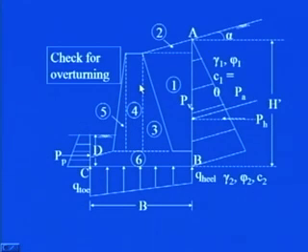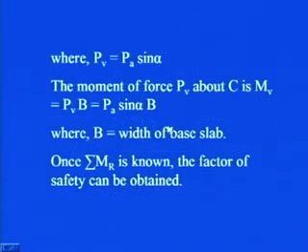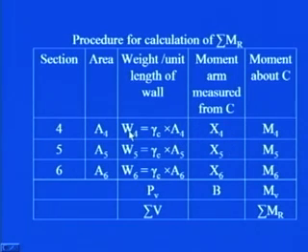That is the area of section 4. Multiply that by gamma of concrete if it is made up of concrete. If it is made up of stone masonry, you have to multiply the gamma of stone masonry. So, accordingly, whatever material that you are using, simply multiply the area by the unit weight of that particular material, and that will result into the weight of the wall of that particular sectional area. Then its weight will be acting midway of this particular thickness. So, we know this particular width as we have proportioned, and then half of this particular width will be giving you x4, that is this one. You multiply W4 into x4, you will be getting M4.